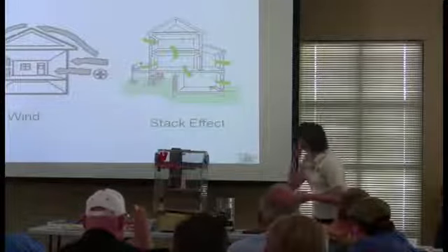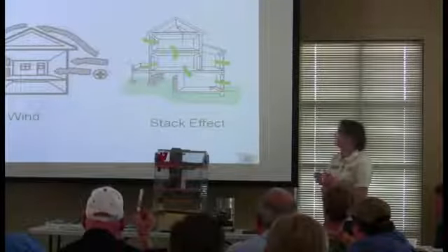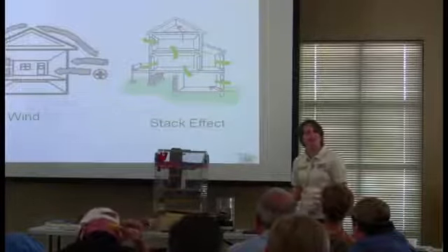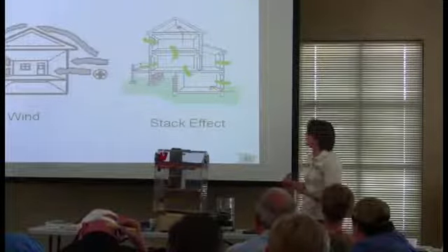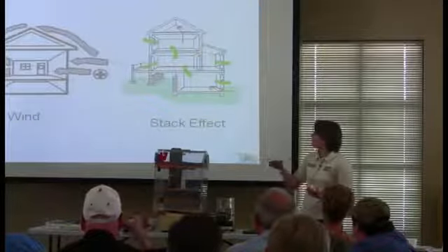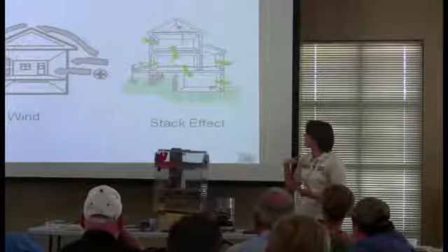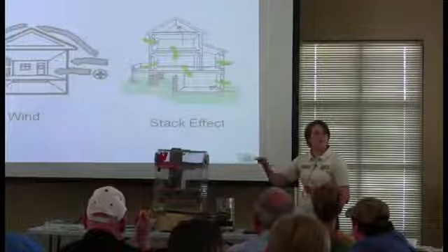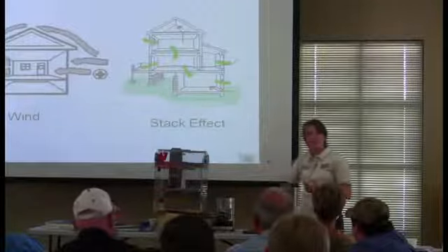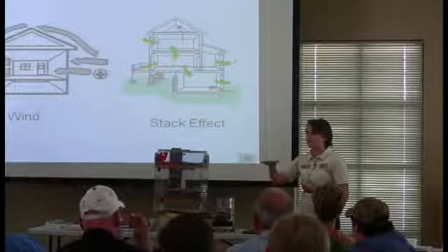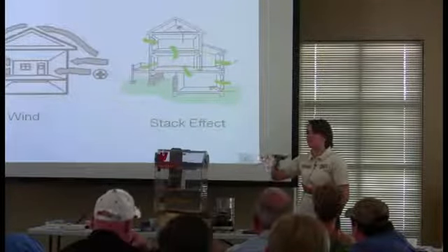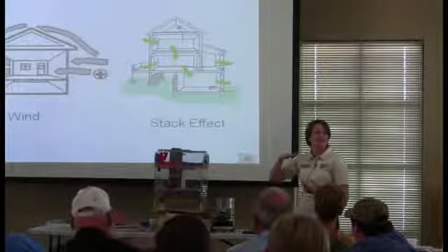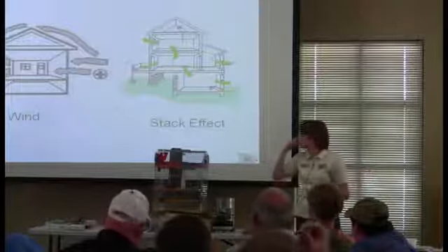And so there you go. Mike's drawing it for us here. At the very top of the house, we have the most positive pressure. At the bottom of the house, we have the most negative pressure with that stack effect. And then there's this neutral pressure plane that happens where there is actually no pressure difference. Although it's really positive up top and really negative below, there's absolutely no pressure difference right in the middle, which means that even if we have a hole right there, that phenomenon, let's call it, there's no leakage. This is really trippy. It is.